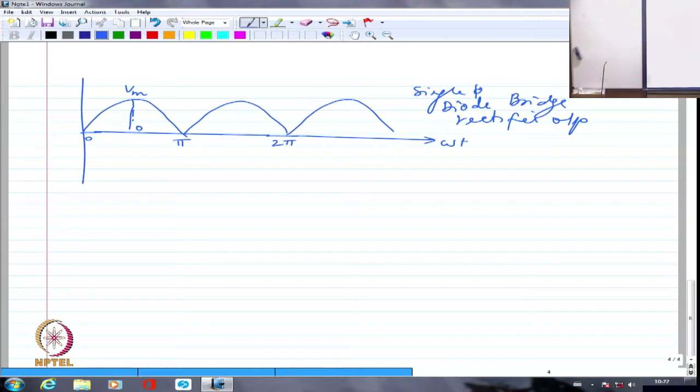Everything will lead to huge amount of vibration and noise. So single phase rectifiers are hardly ever used in a DC motor drive of very large capacity because of this reason. If it is a large capacity drive, the vibrations normally will not be tolerated so much.